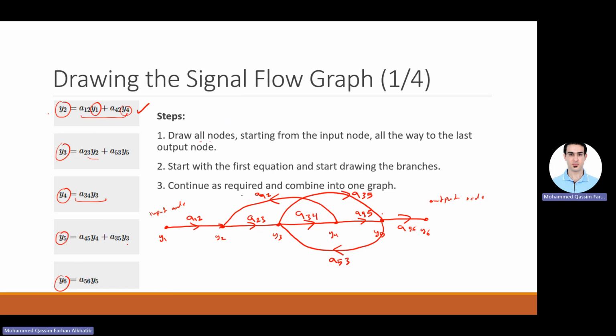No. So you're talking about whether the gain here is going to be positive or negative? No. So A42 is a constant. It could be negative, could be positive. So don't usually think, oh, if the arrow is going there, so that's -3. No, it doesn't have to do with that, because it depends on the adder itself. If the input of the adder, like this, is positive and that is negative, and the block diagram was 3, then yes, I will put a -3 like this. It depends on the adder. So in this case, we are under the assumption that all adders have two positive inputs.